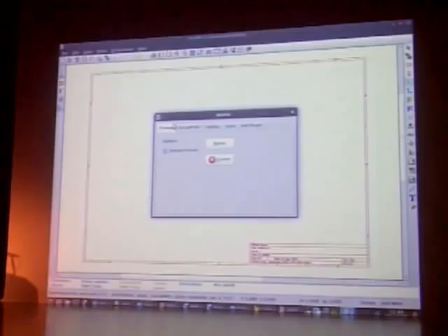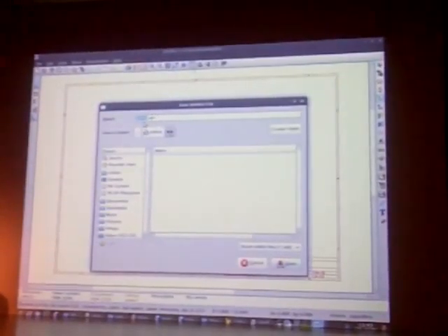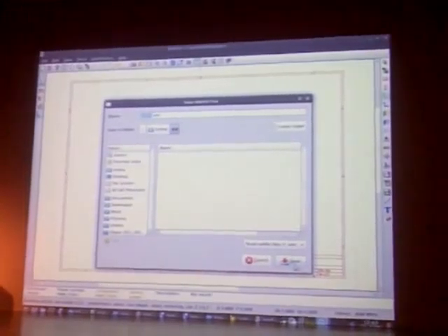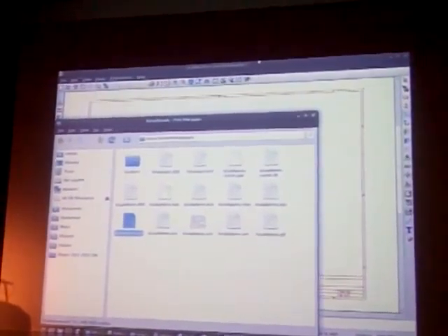So that's our schematic. Next thing to do, we have to export our netlist. So we're going to generate a netlist. It's going to ask us for a format. We'll take the default. And yes, I'll call it buffer.net. I export it. Bang. We've got a netlist. So we're done with the schematic.